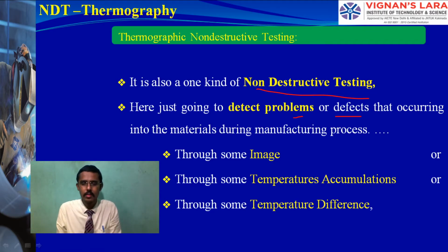If high temperature is induced there, definitely there will be a problem or otherwise a defect, because high temperature obviously creates martensite formations, loss of properties, crack initiations, breakages, or erasing of magnetic properties.